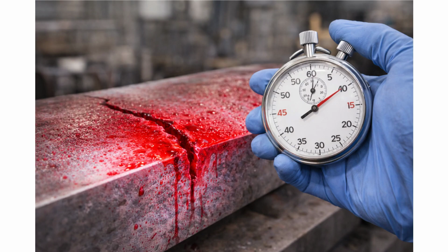Step 3 is where patience becomes a virtue: dwell time. The penetrant is allowed dwell time to soak into any flaws, generally 5 to 30 minutes. This is the waiting period where the magic happens. During this time, capillary action draws the penetrant deep into any cracks, pores, or other surface defects. The longer the dwell time, the deeper the penetrant can penetrate.